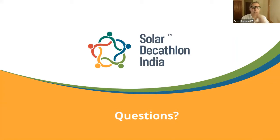So temperature matters, but it's not everything, and we can deliver the comfort that's needed. In your decision making, you should talk about what the temperature should be. The closer the set points are to the outdoor condition, the less energy you're going to use. So there is a little bit of incentive to go with higher temperatures on the cooling days and lower on the heating days, but don't go too far with it, would be my recommendation. You don't really need to.